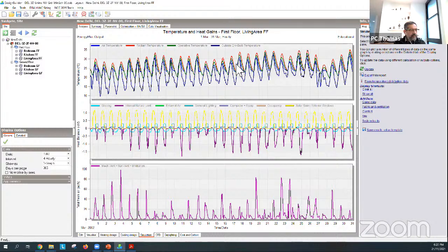If you see this week here, you can see that every day is slightly warmer. So these 4 or 5 days, the outside temperature is getting warmer up till that point, and then drops off and then starts up again. But anyway, you can see here that at some point, the outside temperature starts to fall, but your air temperature and your radiant temperature continue to be above the outside air temperature and reduce slowly.